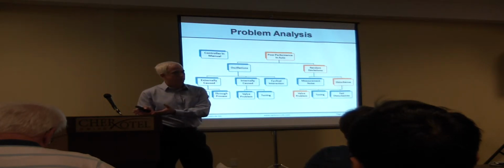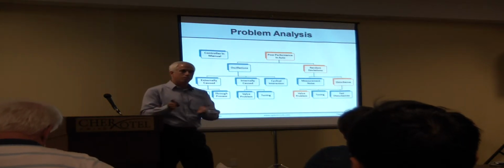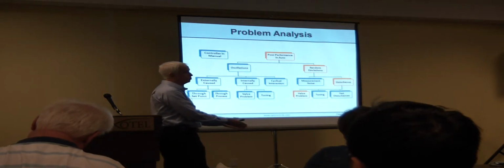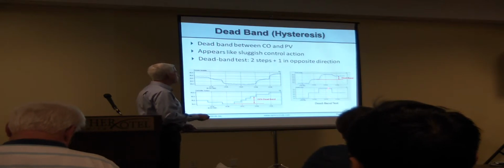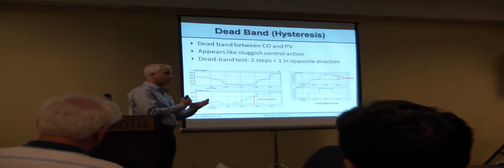And then finally, disturbances. We've got this disturbance. It's affecting the process. Not much we can do about the disturbance. That's just part of the process design, but it sure is affecting our loop here much more than we'd like. Could be a valve problem, tuning problem, or it could just be that this disturbance is way too fast for the loop to handle. A valve problem typically would just be a deadband problem.